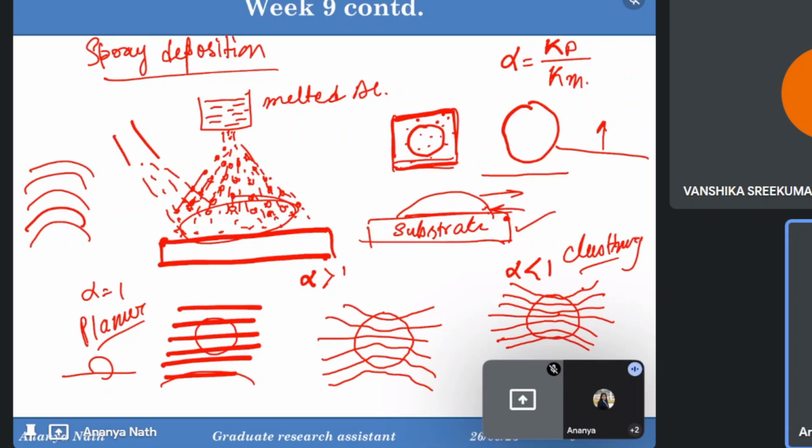Then come the 3, 4, 5 series, dealing with magnesium, silicon and manganese. When we add magnesium and silicon both together, we form the 6000 series, which is a known heat-treatable alloy, because Mg2Si can be formed as a precipitate, and that will lead to the strengthening. But in the case of 3, 4, 5, precipitations are not formed. Si itself cannot form any precipitation, neither can the magnesium.